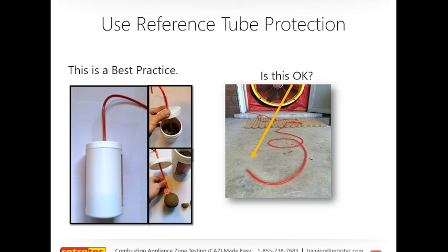So what I like to do, and this is my opinion, is I like to use this guy right here. Actually, my friend Pete Kutcher made this, and it's a genius idea. Inside of it, we have just a tennis ball. This tennis ball has been perforated. I have a bit of pressure tube in there with what we call a bulkhead or a pressure tap sticking out of it, and I've perforated it and filled it with a bunch of larger rocks, not small rocks, because small rocks will get into the tube and mess it up.